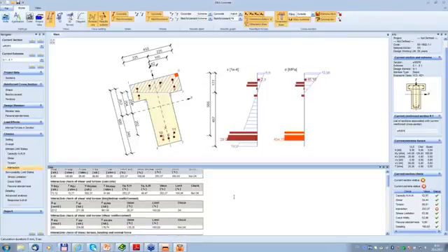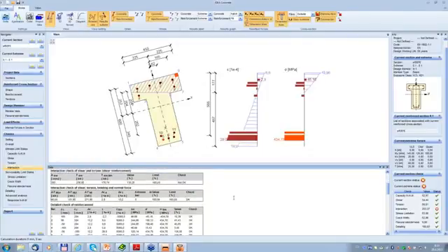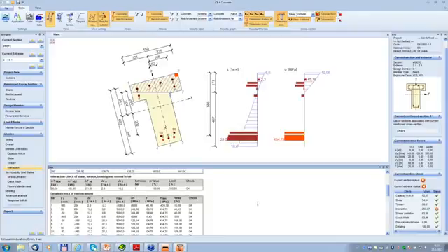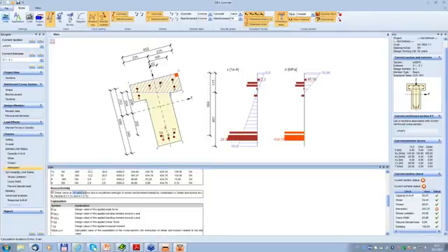The program even tells you these are intermediate results, and the program tells you the shear check is not satisfactory due to insufficient strength of shear reinforcement loaded by combination of shear and torsion according to clauses 6.2.3 and 6.3.2. So you immediately know that you have to change the reinforcement.